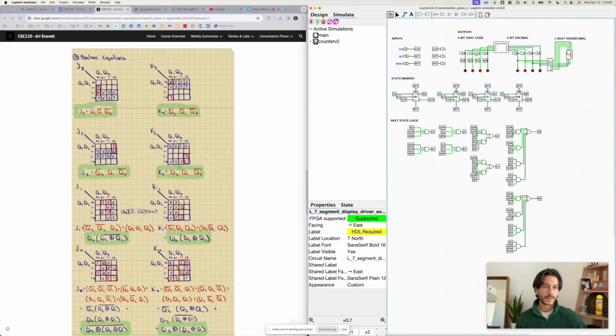From most significant to least significant as you read it left to right. The LEDs are just user interface because I thought that these pins were rather small, so this was much easier to indicate a higher or lower to the user. Here's the gray to binary converter I created. 4-bit decimal here on the right, most significant to least significant as you read it, along with the LEDs.